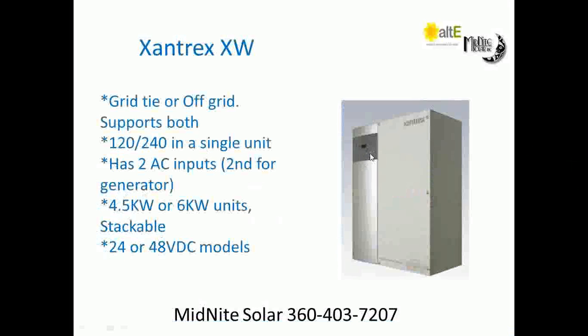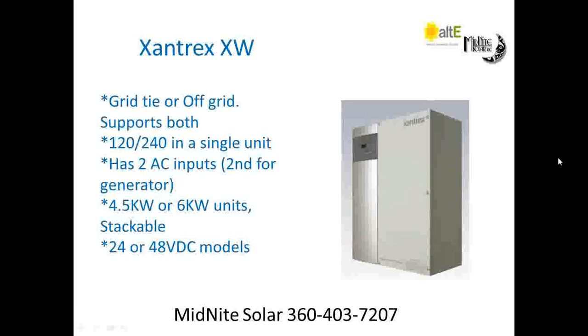And unlike the Radian, if you wanted the Xantrex to just work and just make power, and didn't care about selling or any of the other stuff, it does have a very, very basic display on it that allows you to turn the inverter off and on and monitor a couple things on it and make it an inverter. So if you wanted to just power your house from this and didn't care about grid tie or any of that, you could install the Xantrex right out of the box, just push the on button and have AC power.